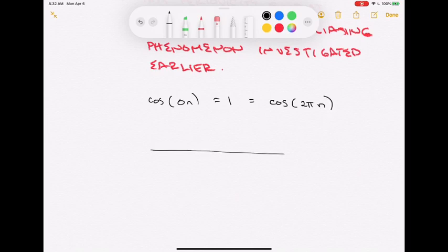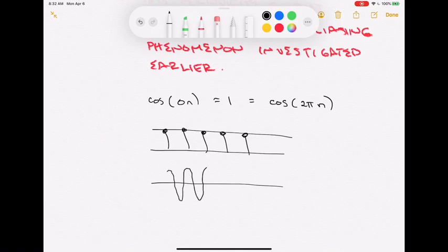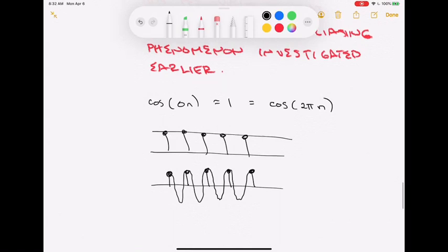So I could have a signal that was DC, that I get samples of 1 with, DC signal coming out of there. I could have also had a signal that was oscillating once per sample, and we'd also get those same values. So that's that aliasing phenomenon. This is omega equaling 0. This is omega equaling 2 pi, if you will. And if we can't tell the difference in the signal that's going in, we're not going to be able to tell the difference in the signal coming out. That tells us that that frequency response is going to be 2 pi periodic.